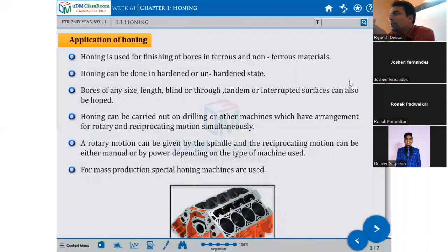Crankshaft, your drilling machine. Drilling machine table, what happens? When you rotate, it's coming up. When you rotate in the opposite direction, anti-clockwise, it's going down, up and down. So there is again a motion change. There is a rack and pinion arrangement. On the machine column, there are straight teeth, the rack. And the pinion is on your table. So when you rotate that pinion gear, it meshes with the linear rack, so it is going up and down.